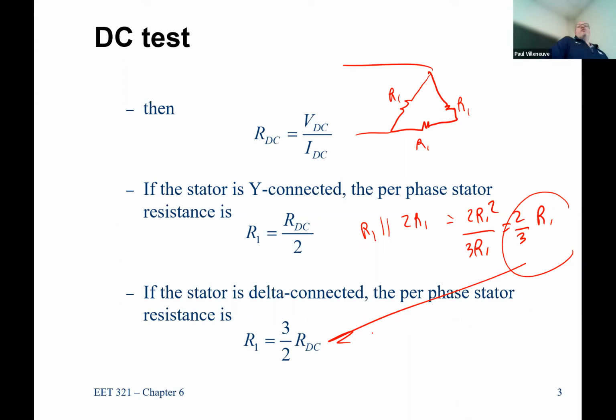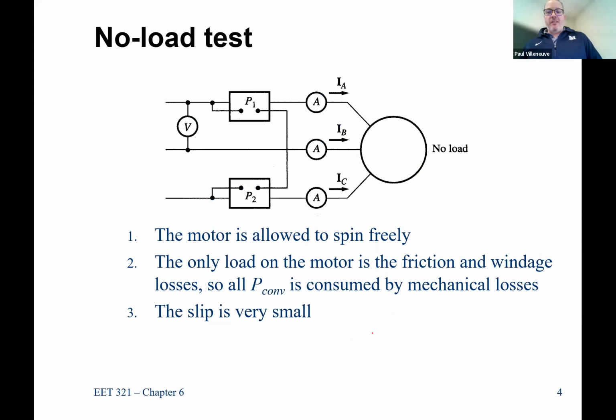It's the same thing with the transformer. If you're buying less than a 5 MVA transformer, those are kind of standard off-the-shelf items. So you just get what you get, and they would give you some typical data. They might not give you a full-blown factory acceptance test, because a factory acceptance test costs a lot of money. It's not cheap. So if you don't need to do one, don't do one.